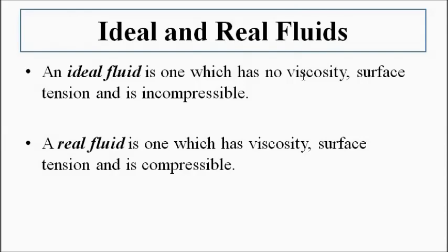One bottle is filled with water, another bottle is filled with, let's say, tomato ketchup. Now if we turn the bottles upside down, the water will flow easily, but the ketchup will not have the same kind of mobility. This is because the sauce is more viscous than water. Viscosity is that property in fluids which opposes motion, resists motion.